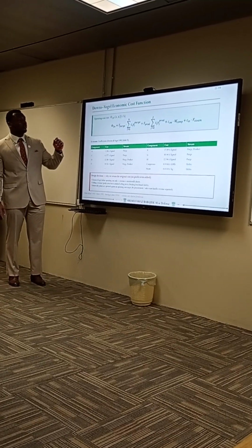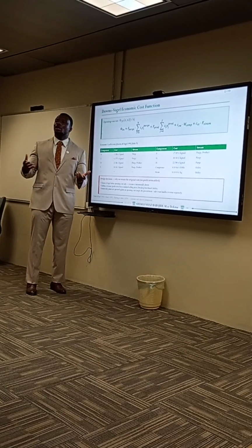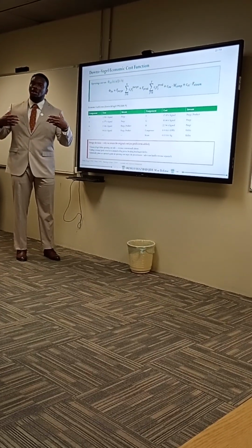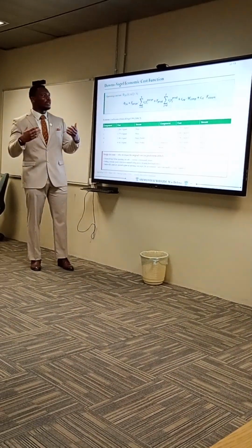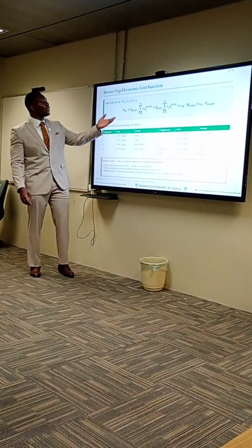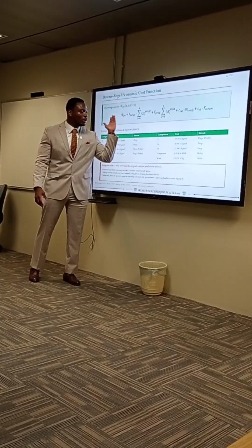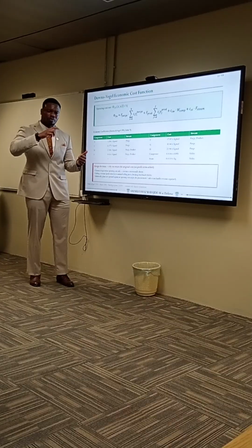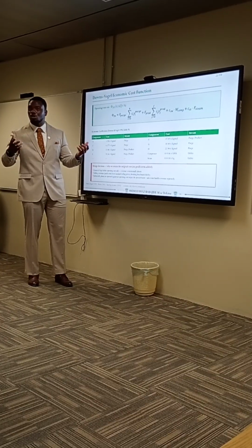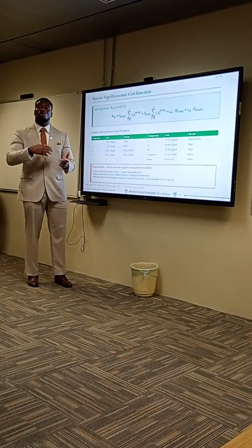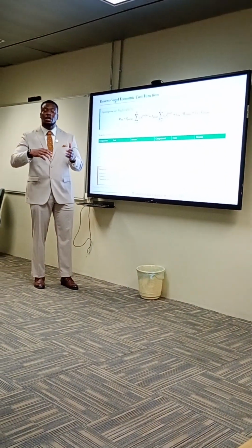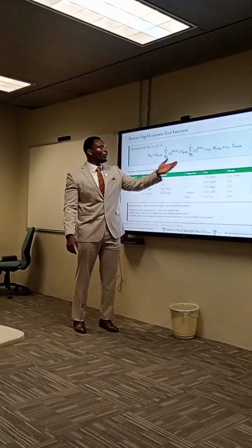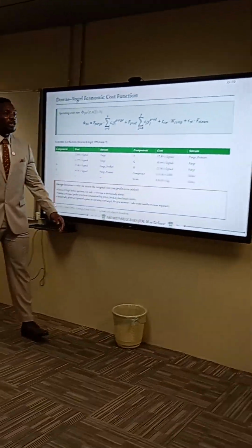And of course, this is the cost function, which is our primary interest here. We're running an operation for 72 hours, 24 hours. What are the metrics we use to define our cost of operation? Every plant has this; you need to keep track of how much you're using to produce. Downs and Vogel introduced this, and it runs strictly based off your purge. Your purge is the amount you send out when you recirculate within the plant, trying to purge out some inert gases. When you do that, you purge out some important reactants as such. And of course, you have the production rate, the cost of steam, and the cost of your energy within the plant.